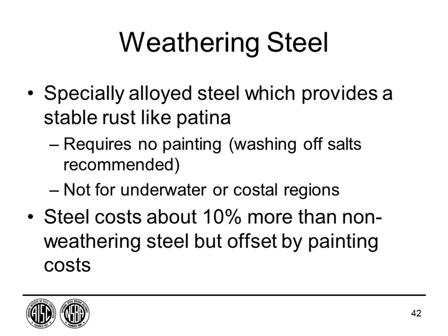It is good to wash off the salt, but it's not for underwater or coastal regions. It really won't perform any better if it's underwater. It costs about 10% more than non-weathering steel, but that's more than offset by the lack of painting. So if you don't have to paint it, the cost is about the same as a painted steel. And so it's really cost effective because it also eliminates any field painting. There's no reason to do any maintenance on this after it's put in service.